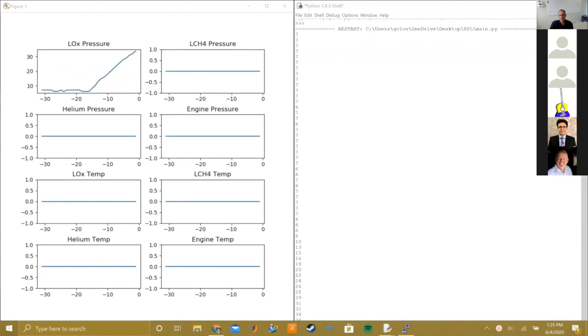rising, and as it does, the axis on the left, the y-axis, is auto-adjusting to scale with the range of data that it's showing over the last 30 seconds. As you can see, it just went from having 10 psi between each tick to now having 20. And then I've turned the compressor off and I've just pulled the plug that is depressurizing that chamber. So it is returning back down to normal.